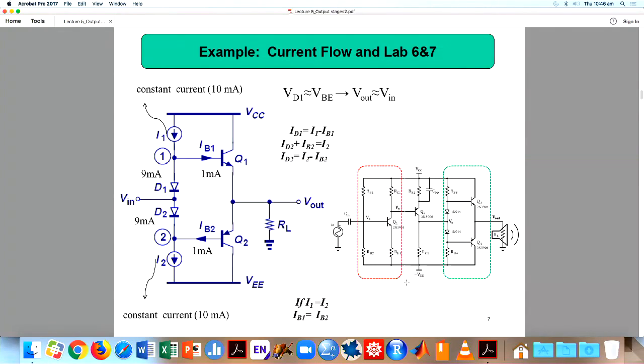So today you both got some work. You have to breadboard the circuit and then test it. See the signal here and then see the signal here. Will you get any amplification? Because this is a multi-stage amplifier. See, the lab name is multi-stage amplifiers. So this is an amplifier, this is an amplifier, and this is obviously a current amplifier. Definitely this is an amplifier, but it will also do some level shifting. So amplifier plus level shifting. That is the reason.